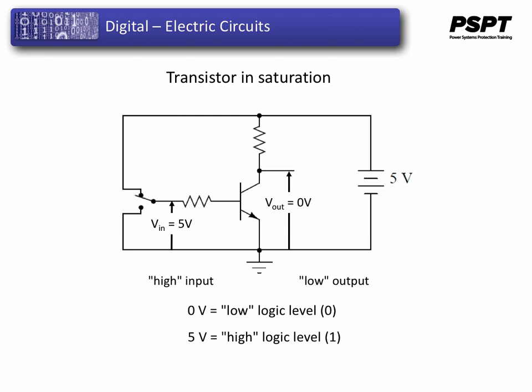Any voltage close to full supply voltage, measured in reference to ground, of course, is considered a 1, and a lack of voltage is considered a 0. Alternative terms for these voltage levels are a high, the same as a binary 1, and a low, the same as a binary 0. A general term for the representation of a binary bit by a circuit voltage is logic level.